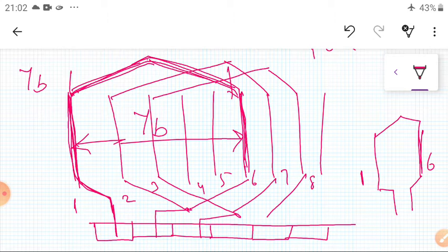Okay, now similarly after completion of this one, next it has to connect to this coil. So it has to come here. Here this is known as the front pitch, YF. What is that? It is the distance covered by the front end connections. So here we are connected to the front connections. This is a back pitch, this is a front pitch.